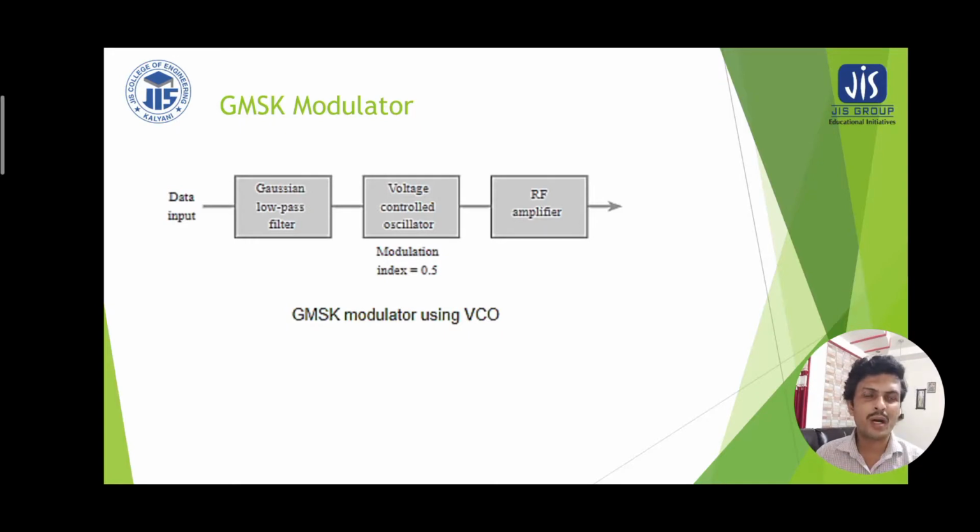It looks like one half of the sinusoidal wave, either the positive half or the negative half. So here the Gaussian is considered as the positive half of the sinusoidal wave. There is a smooth transition of the rectangular edge, that is the positive edge or negative edge of the rectangular pulse has been smoothed out. Therefore, it will be a smooth phase variation. So the main purpose of the Gaussian filtering is to smooth the rectangular data.